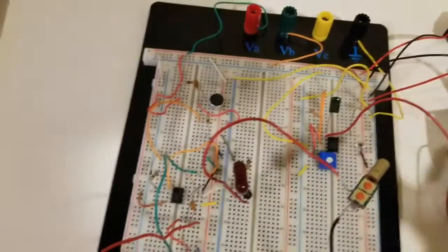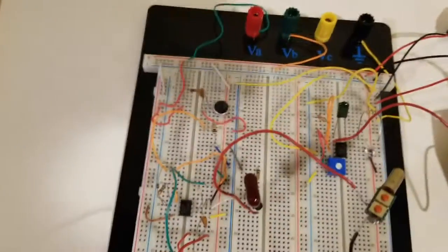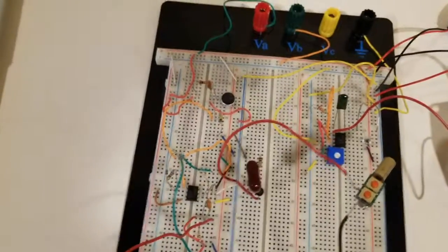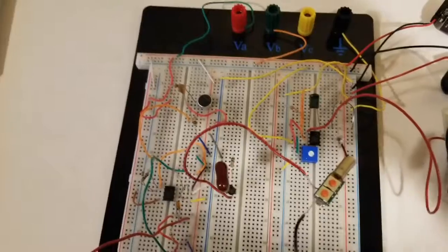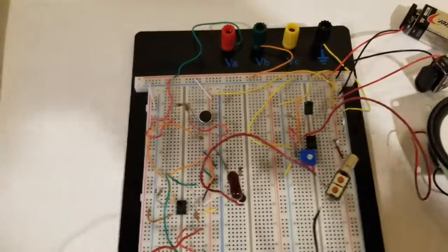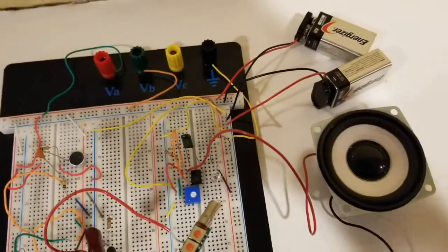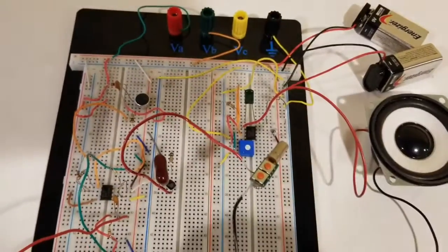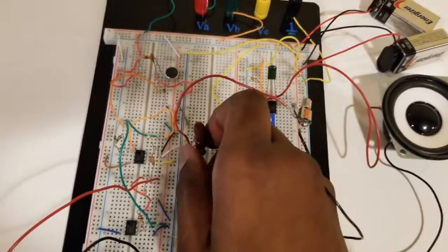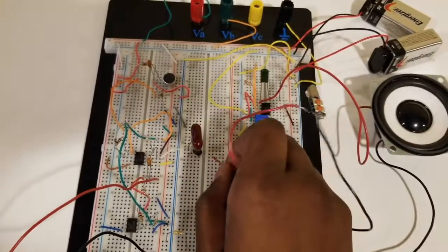The problem with our circuit is we weren't able to get enough gain, and it may have been because of the op amps that we were using, or whether we were using enough op amps, or if the current was high enough. But if you put your ear to that speaker, you'd actually be able to hear it. And just as proof that the audio is being transmitted via the laser, I can put the speaker into where the laser is.